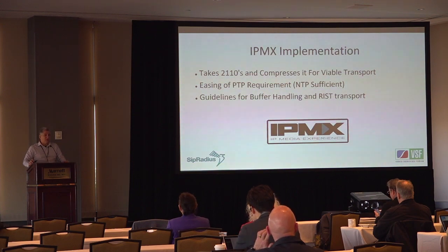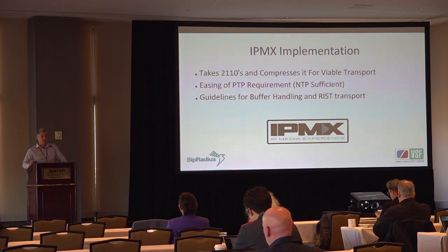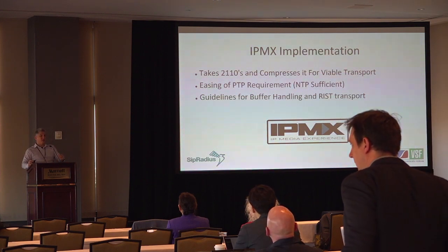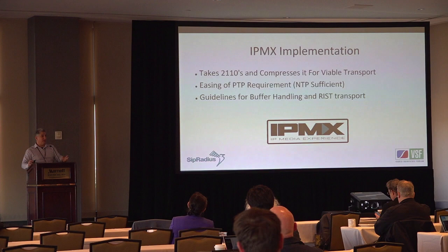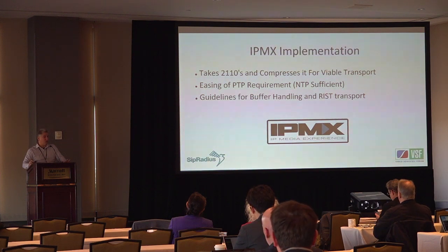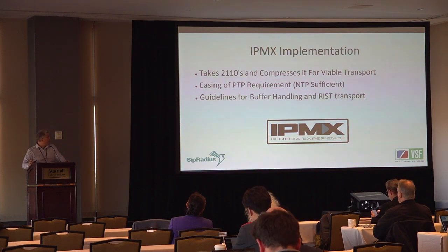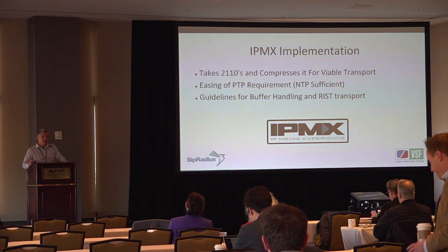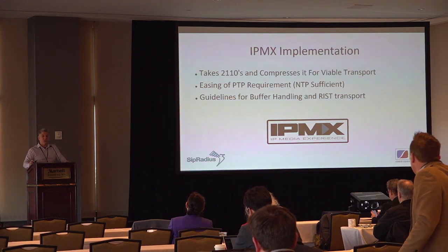In the VSF technical recommendations for IPMX, NTP can be substituted for PTP, and we do that in the other steps of the chain. In addition, though the demos and everybody has focused on JPEG XS as the codec for compression, the spec doesn't restrict you to that. In our case, we had to use H.264 to achieve viable compression for transport to the end users in the different places.